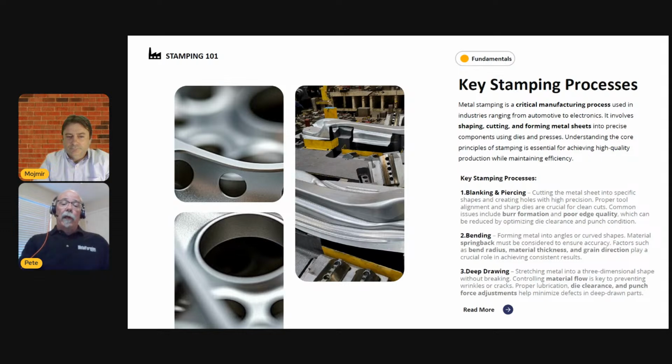Another source is what we refer to as tipping moments in the die. So I have a pad of paper here. This is my die. If I have a high load working over here on the die, especially a progressive die, that generates a larger load, it's going to want to tip the die. So when that die tips, the punch that's mounted on this side over here is going to tip as well. So we're going to have this tipping moment. Even though the die in the die set is aligned, the press is causing some misalignment.